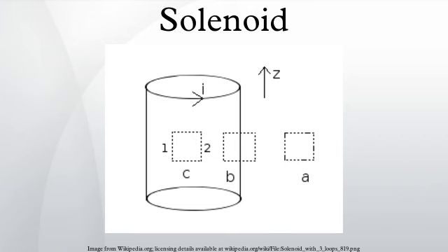Hydraulic solenoid valves. Hydraulic solenoid valves are in general similar to pneumatic solenoid valves except that they control the flow of hydraulic fluid, often at around 3000 psi. Hydraulic machinery uses solenoids to control the flow of oil to rams or actuators. Solenoid-controlled valves are often used in irrigation systems, where a relatively weak solenoid opens and closes a small pilot valve, which in turn activates the main valve by applying fluid pressure to a piston or diaphragm that is mechanically coupled to the main valve. Solenoids are also in everyday household items such as washing machines to control the flow and amount of water into the drum.